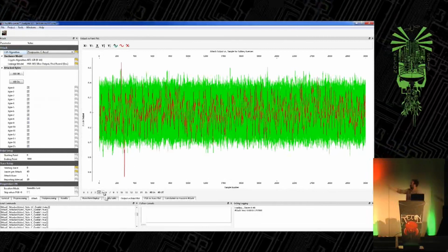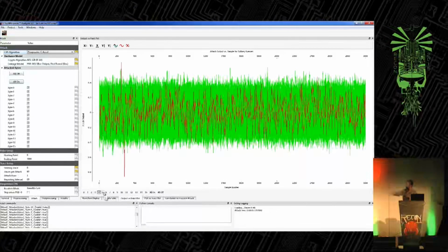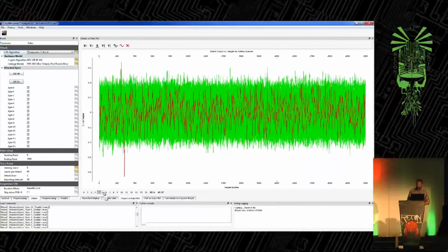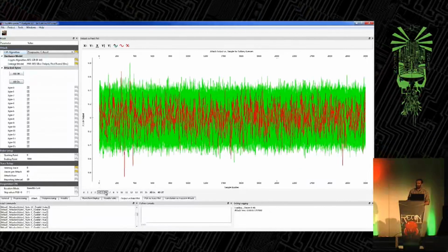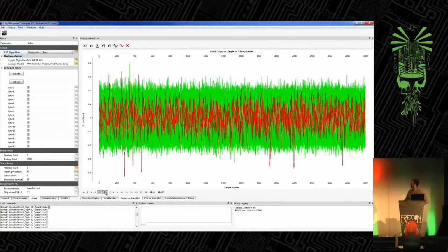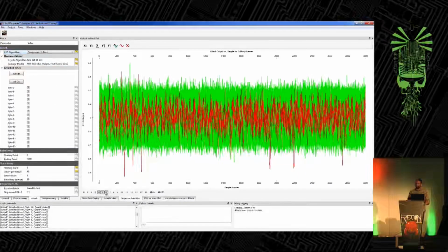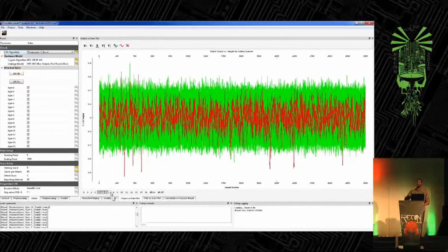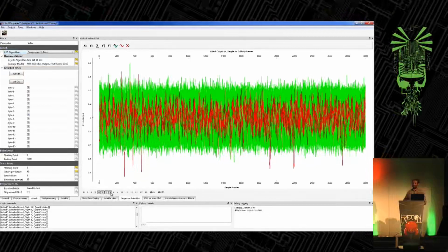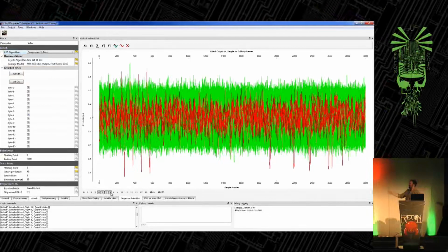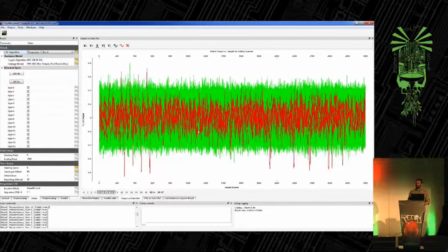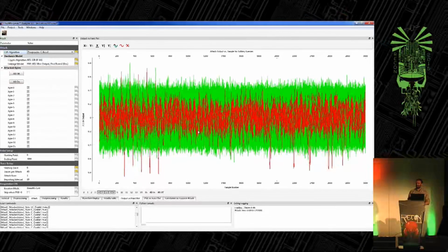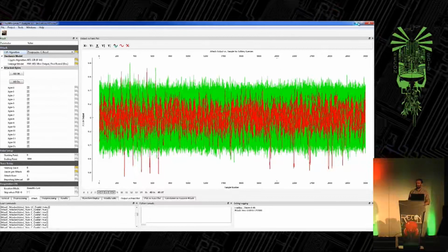So this is recovering byte 4. If I look at recovering byte 5, you'll see that peak marching on in time. This is because it's an AES software implementation, so it's doing byte 5, byte 6, byte 7. You can see the specific instance in time where that operation of interest is occurring. So it also gives you some information about the underlying process.